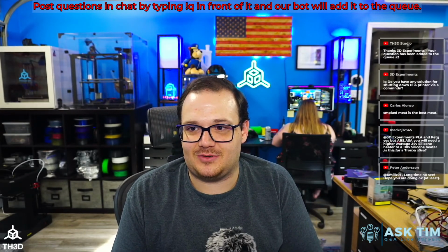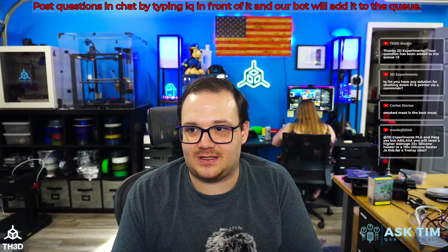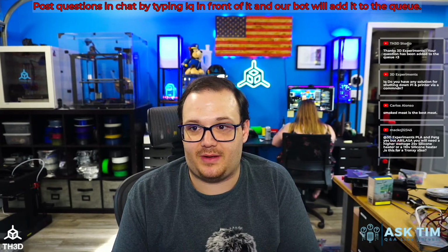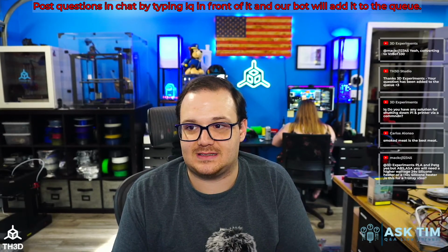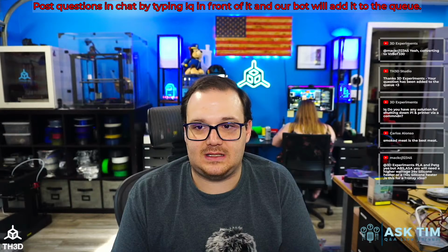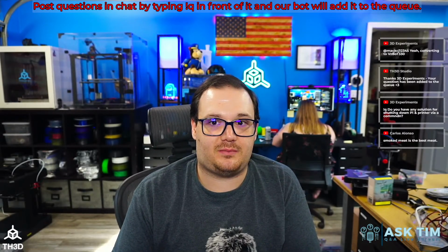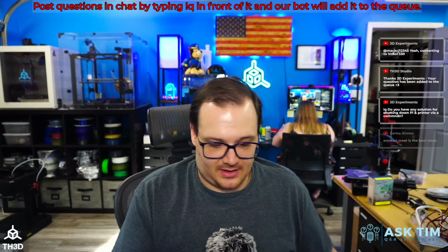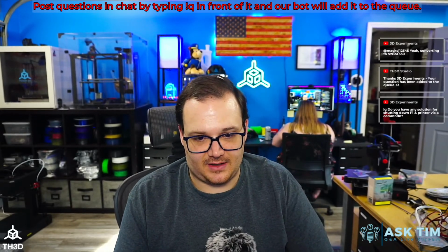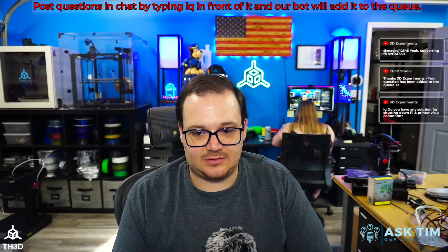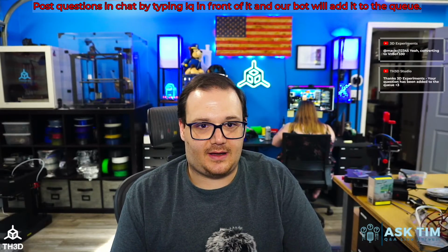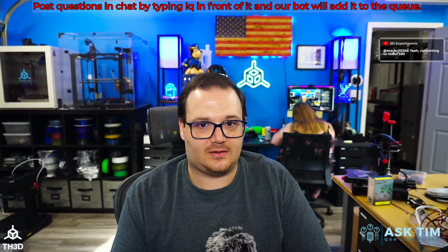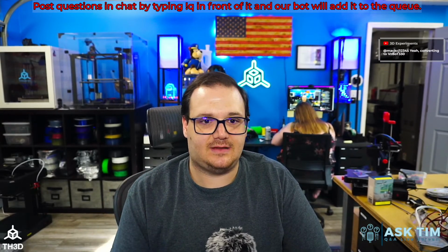He says, does the EasyBoard V2 support any other 128x64 LCD besides the typical blue backlit one, when I want to run a small Voron style LCD? You could if you figured the pinouts out, and the pinouts are actually documented in the pins file. Basically, you would want to run standard Marlin because you're completely DIYing it, or you can look at our code and figure out where we're setting the LCD values.